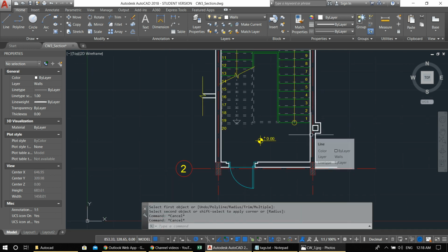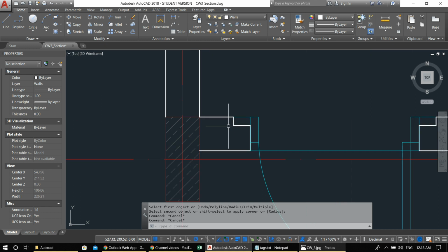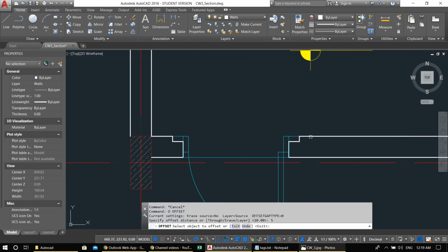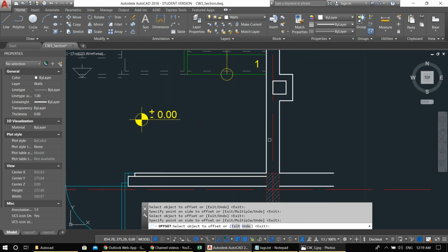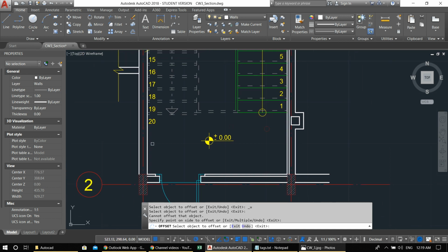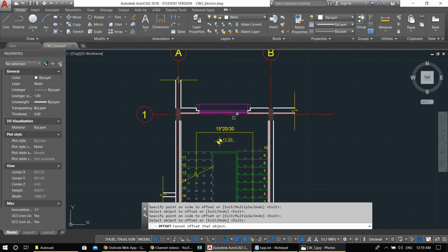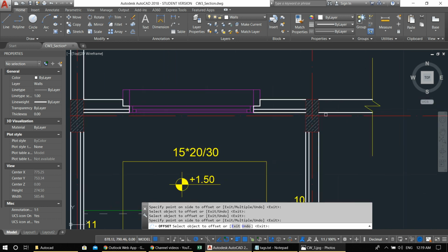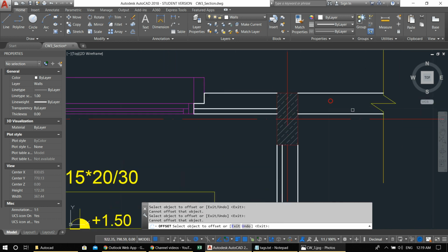And then we have details of the finishing of the wall. So you can have, let's say, offset 5 for the wall. I have actually a layer for this called detail. These two might be shear walls, but I don't know. Let's say for now we have a good structural system and none of these are shear walls. So I have a finishing detail for this in the interior wall. So let's say something like this, continuous.